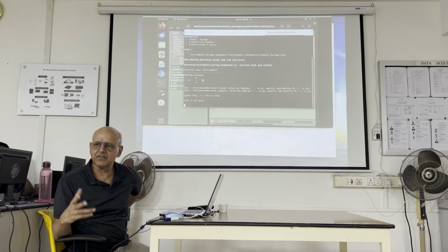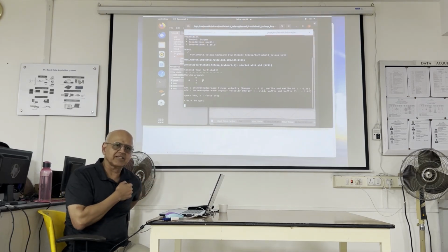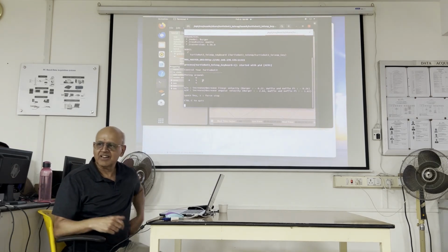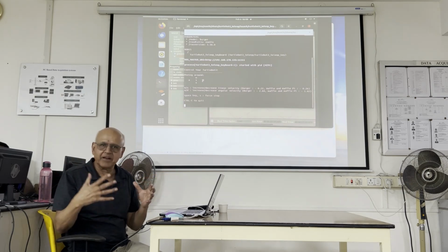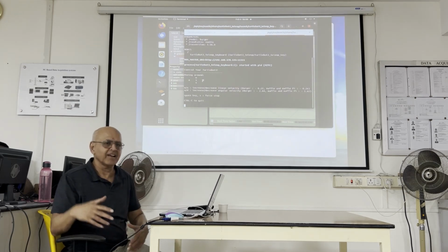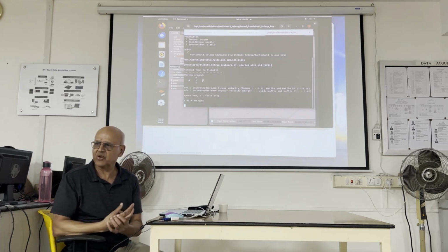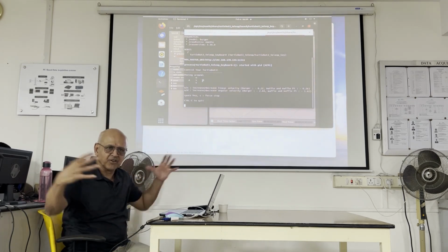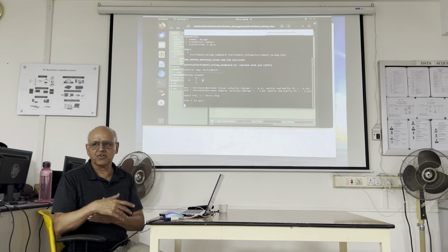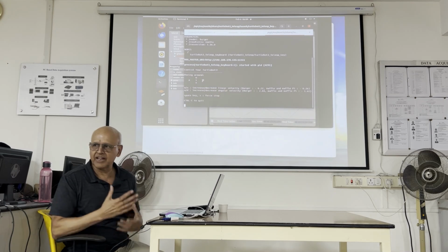Now you're saying, what is the difference, where is he going in a hurry, right? Here's the thing, when you simulate on Gazebo, those squares are 1 meter by 1 meter. So if your robot is going to be slow, you'll have to bring your obstacles in closer, because you don't want to wait 1 minute for the robot to finish the exercise. Because if you make a mistake, you bring it back and run it again, right? So if any robot is going to be that slow, you're forced to create a very small scene. You can't make it big because it's going to take time. So reruns take time. Of course, it's still better than taking the actual robot outside or inside and running it. But I would like a faster robot.